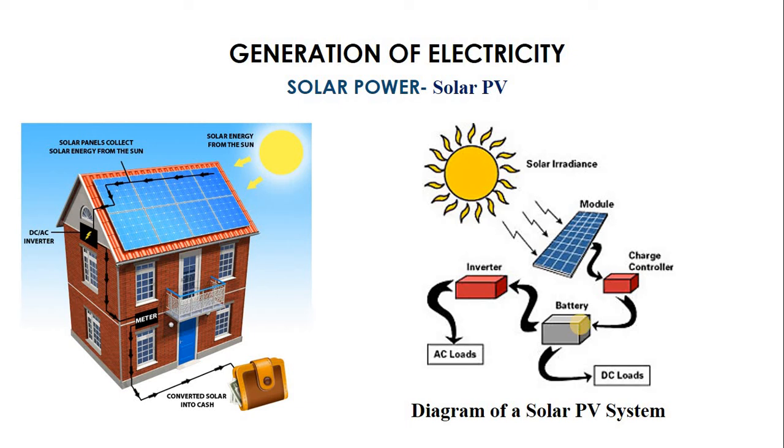Now, when it comes to the point where the sunlight is low and therefore the output power of the solar module drops, in other words, the voltage drops to the point that now the battery's voltage is higher than this. If you don't do something about it, there's the tendency of the battery sending current backwards, because usually when you have two power sources in parallel, the one with the higher voltage will usually tend to push current into the one with lower voltage and charge it.